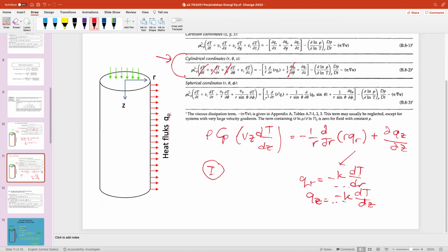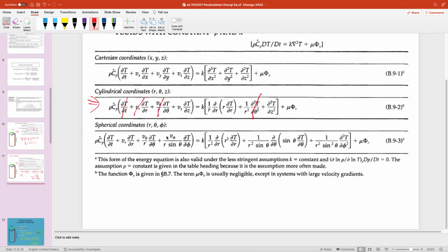So if we put k ∂T/∂r here, and we put the equation for ∂T/∂z here, this becomes this formula as well. Okay, so both sides are going to be okay. But again, let's check, I also forgot what the problems look like later on regarding the boundary condition. If the boundary condition later on is in temperature, then we can use this one, or the previous one, also similar.